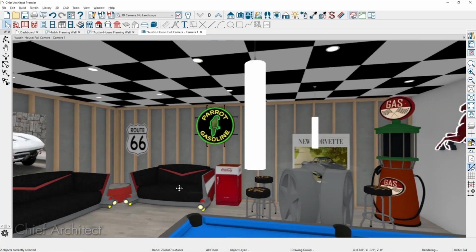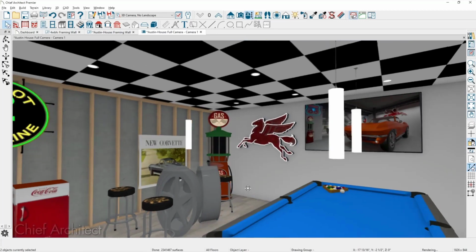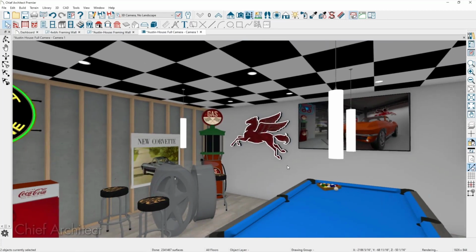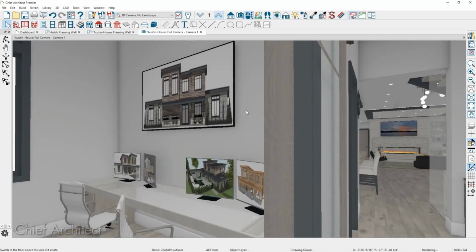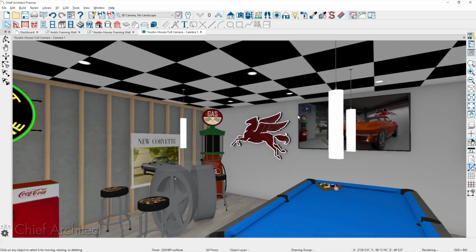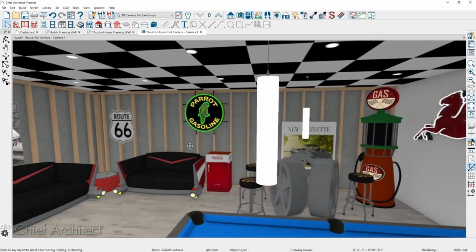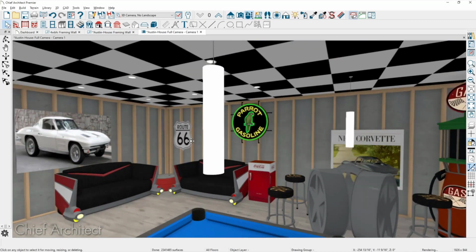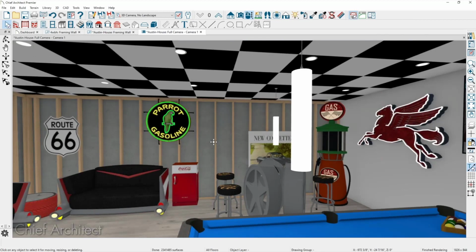So there's our unfinished wall. The back wall was not changed, so there's your sheetrock. And if we go up a story, then using the floor indicator, it doesn't affect those walls because I used a different wall type. So that's one approach you can use to create an unfinished basement with that type of wall type. Does that work?